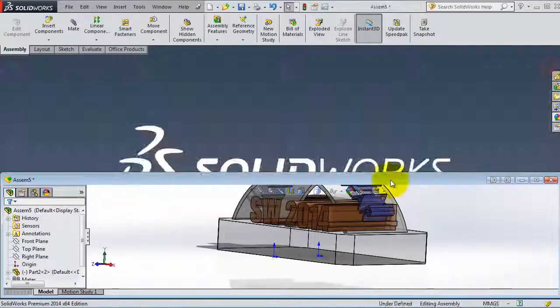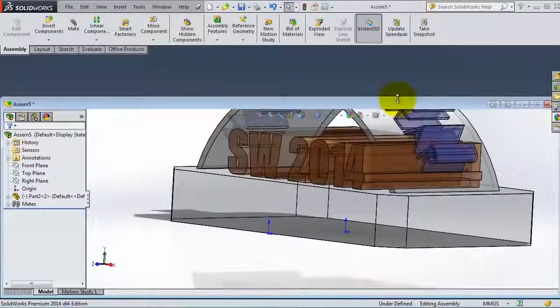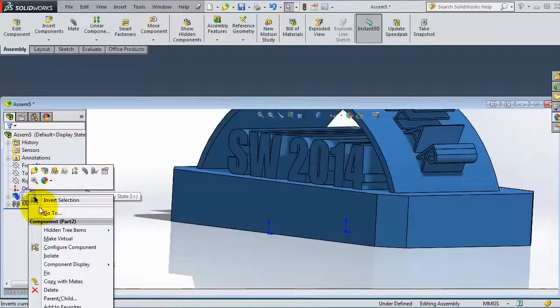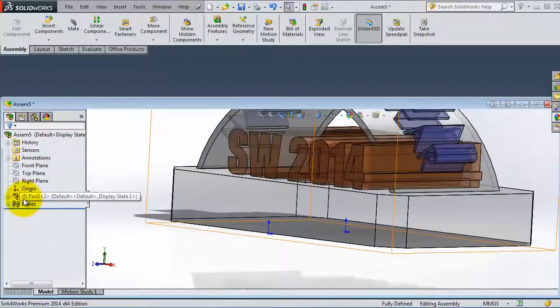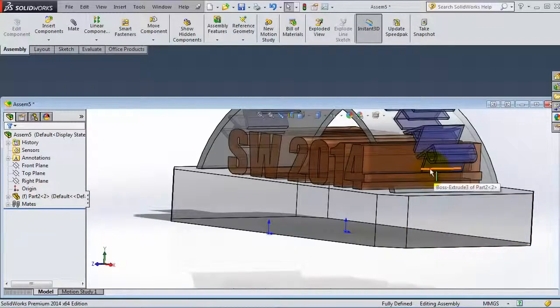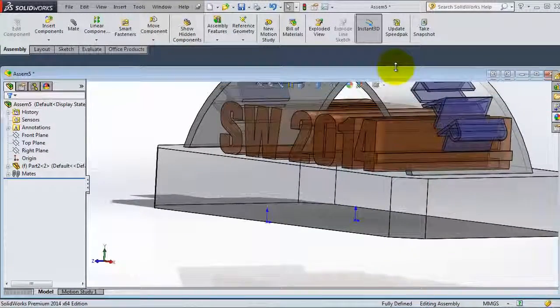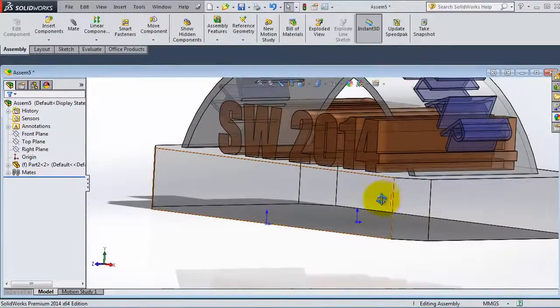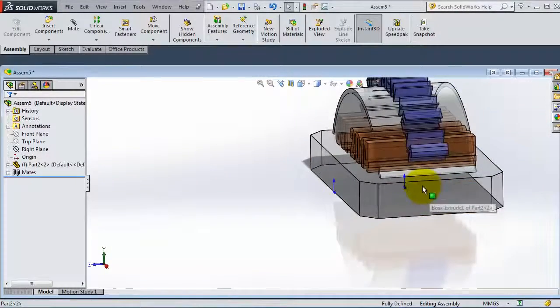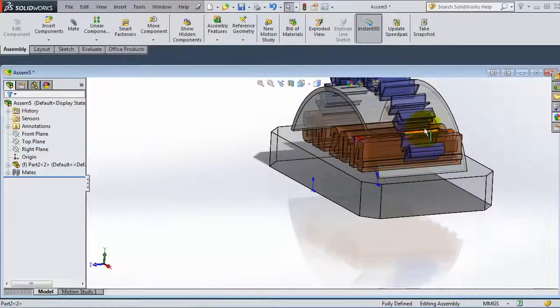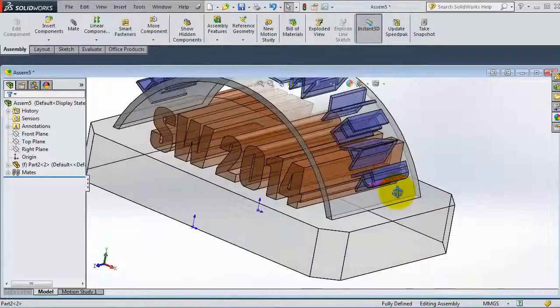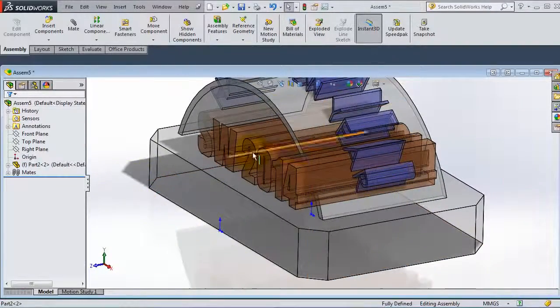And we remember from the previous tutorial that when you are inserting your first part, you will see the F sign at the beginning that indicates that your part is fixed. So this is the meaning of the F. That means you will not be able to move it around unless you float that option.